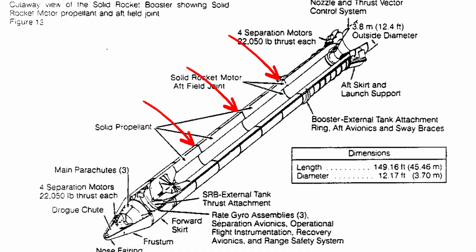And so when you're assembling the rocket, those field joints have to be sealed, because obviously you don't want the hot rocket exhaust leaking out between each of those joints. So there was a process developed, and a variety of structural members were created to help contain the rocket exhaust, as well as putties and a variety of materials.